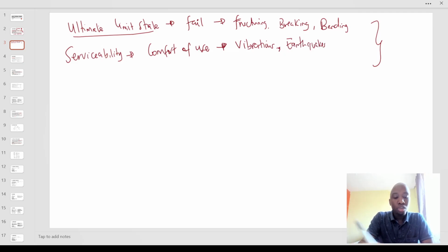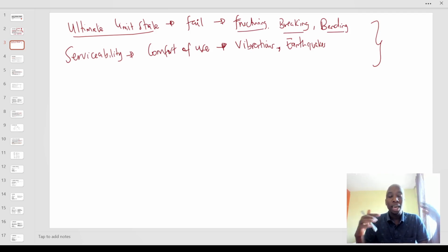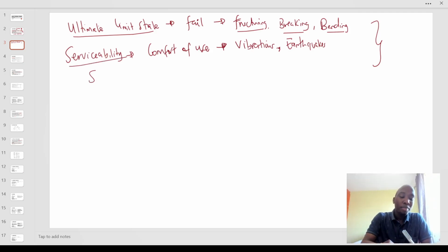So you see, when you talk of ultimate, it's a structure on its own without an external influence. Can it bend? Can it break? Can it fracture? Can it buckle? But when you talk of serviceability, you're talking about service. Even if the structure has not reached its ultimate state, what would happen if I subject it to certain vibrations, certain situations? So those are the two states.